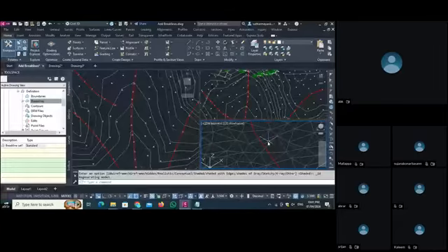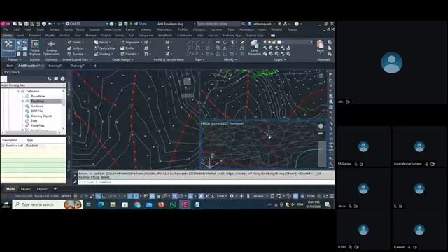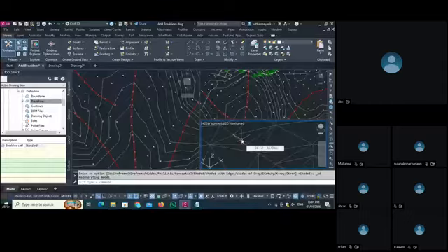And see another red line. So the contour triangles here are big and not connected to this red line, but we chose the mid ordinate as very low for accuracy. See, so the number of contour lines and triangular lines is also increased, and we can set all those lines with our red line too.